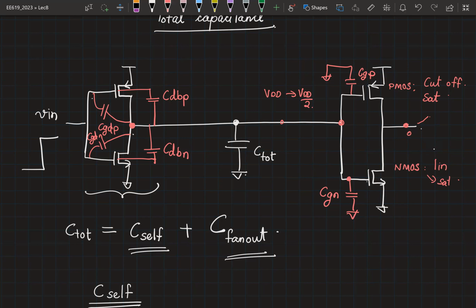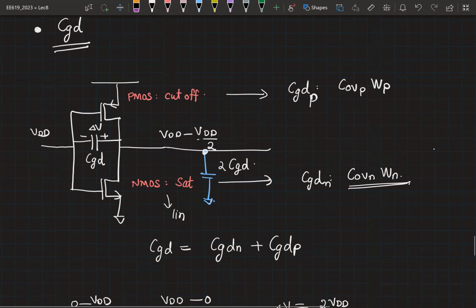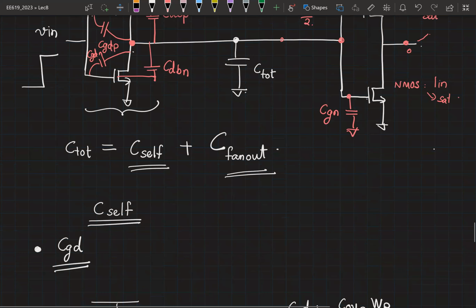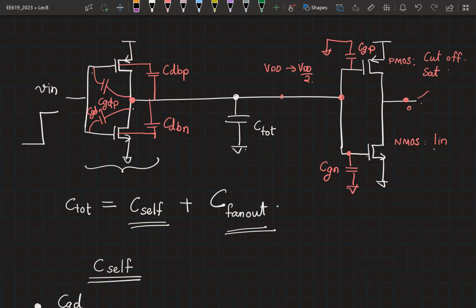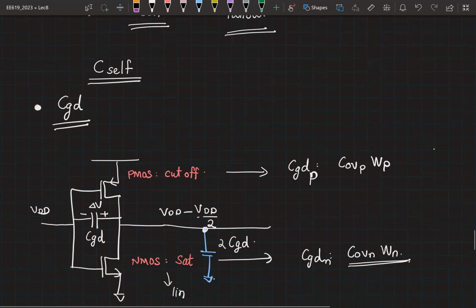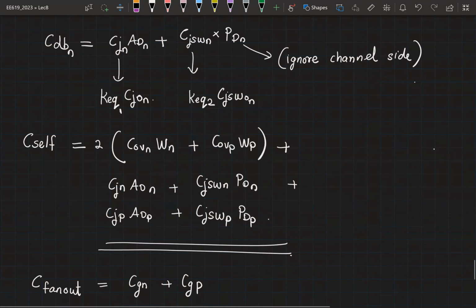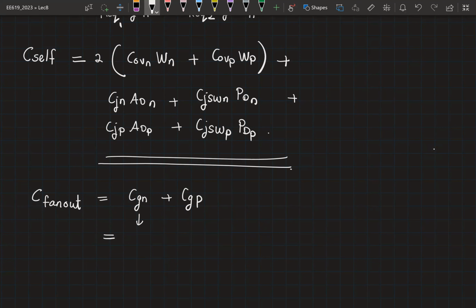And if it enters, then you have to find out the duration for which it is in linear region, saturation region, etc. The drain voltage is very small. Correct. It will remain in linear region. It won't even enter into saturation region, correct? So we'll simply approximate this. You can actually give me the correct value. What would it be? NMOS is in linear region.